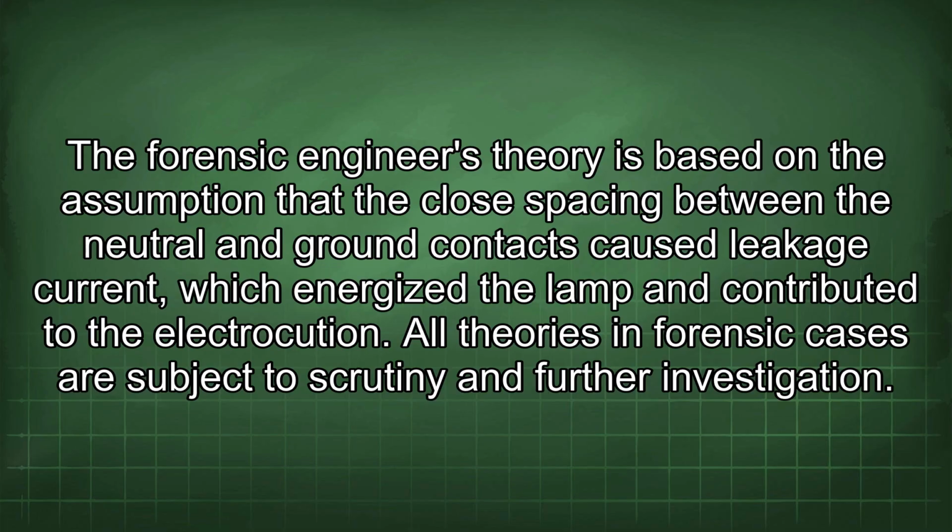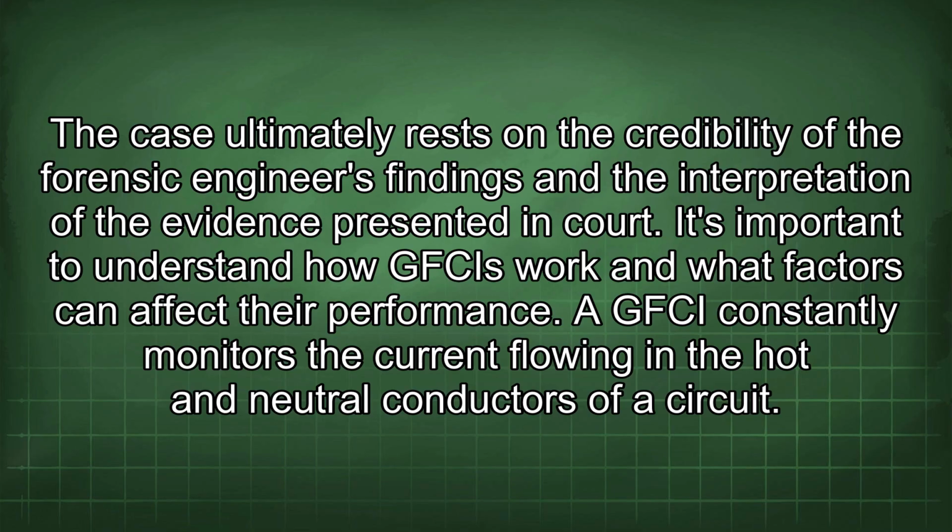The forensic engineer's theory is based on the assumption that the close spacing between the neutral and ground contacts caused leakage current, which energized the lamp and contributed to the electrocution. All theories in forensic cases are subject to scrutiny and further investigation. The case ultimately rests on the credibility of the forensic engineer's findings and the interpretation of the evidence presented in court. It's important to understand how GFCIs work and what factors can affect their performance.